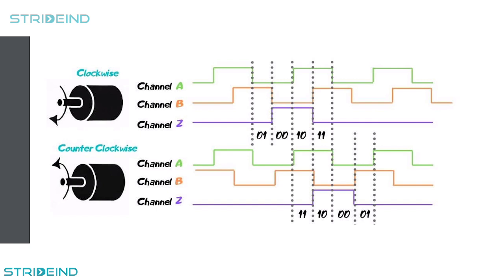What is 1 is you have a positive volt, whatever is based on your encoder, and channel B has 0 volt at this point. Then if you move again clockwise, the next count you're gonna get is 1 1. Both channels will have voltage in the positive phase.